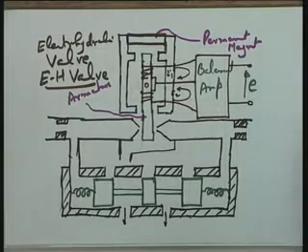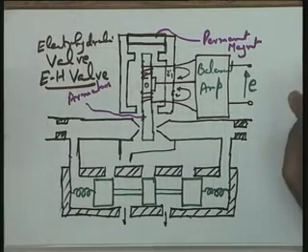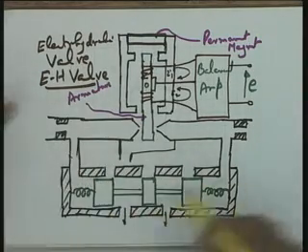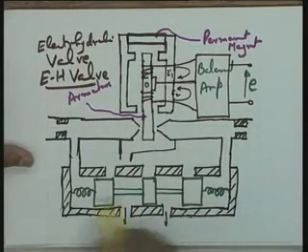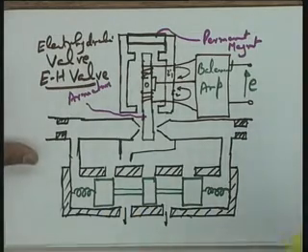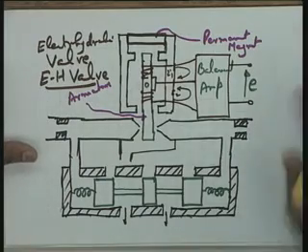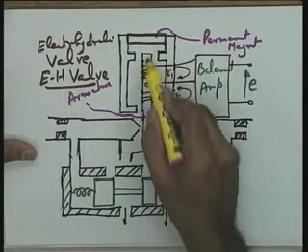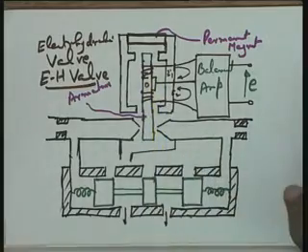Naturally, when error E is equal to 0, you do not want any action to be taken, because when error E is equal to 0, the load position follows the commanded position. So if you do not want any action to be taken, in that particular case, the movement of this spool should be equal to 0, and let us see whether this situation is realized or not. These two currents are equal at the steady position. This armature does not move.